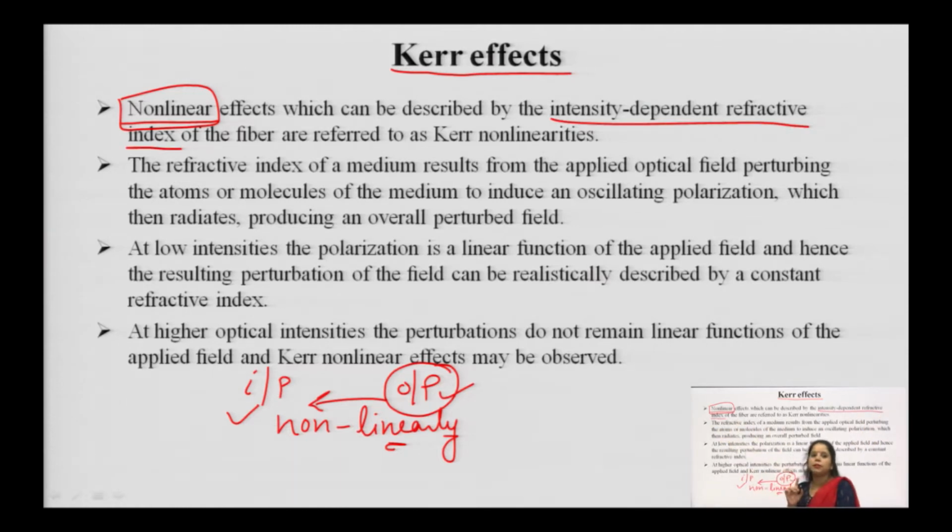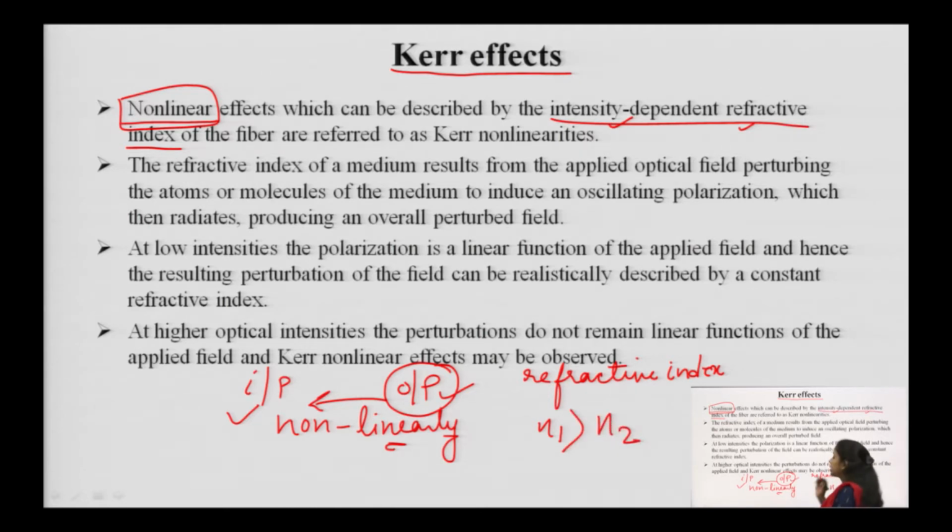This is the main point here: intensity dependent refractive index. Already we have knowledge about the refractive index. The refractive index of the medium decides its propagation form. We know that the refractive index of the core should be greater than that of the cladding for proper TIR, which is the main principle behind optical communication.